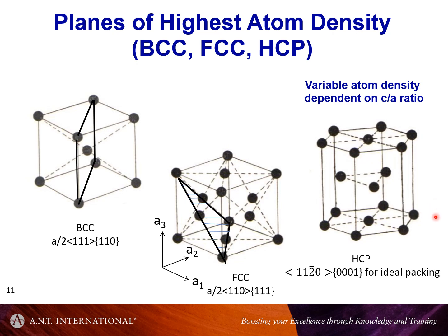Well, close packing is basically a way of describing, if you have atoms, what is the minimum volume that a given number of atoms can be packed into. And often one uses spheres as an approximation, like I use ping pong balls, as you'll see. And the minimum volume for a given number of atoms comes about by close packing spheres in what's called this kind of hexagonal arrangement.